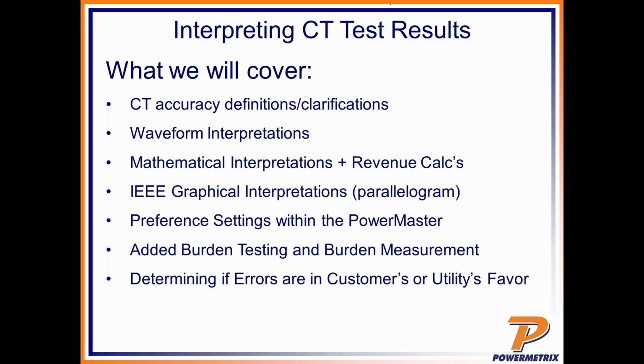Moving on. Okay, so let's get into the meat of this here. There's going to be a lot of theory in this, so I hope you guys can stick with me. It may not be the most fun presentation, but hopefully it's got some good information for you. So what are we going to cover? We're going to cover basic CT accuracy definitions and clarifications of those, okay? And we're going to look at how those clarifications work when you're looking at waveforms, what the math looks like, how revenue is affected, numerically.